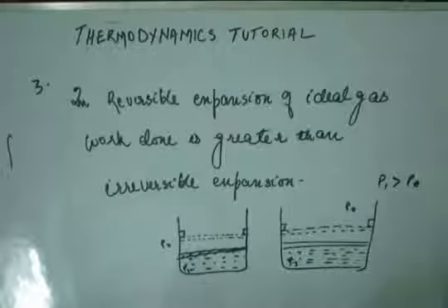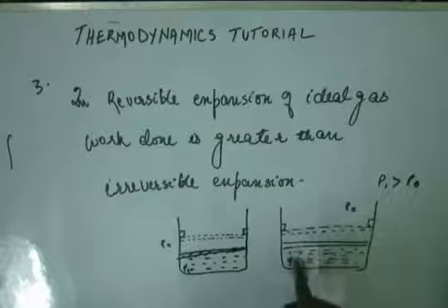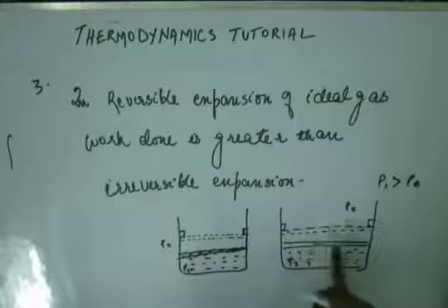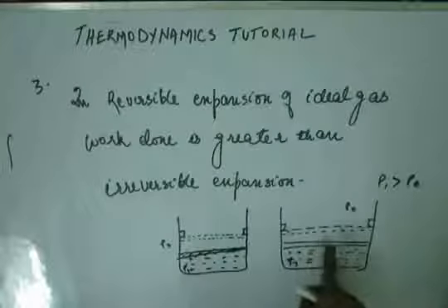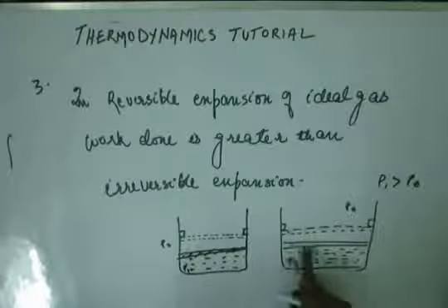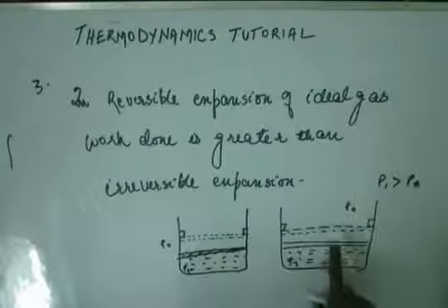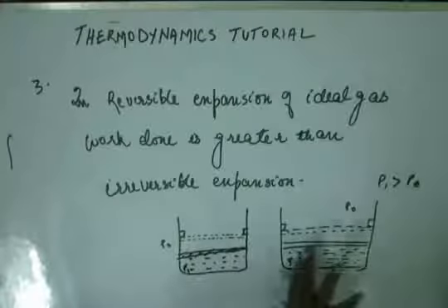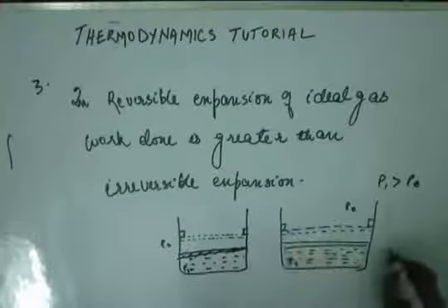Now in this case, if I have to calculate work, suppose the moment I remove my hand, what's the work? The moment I remove my hand, the resistance that the piston has is only the pressure from the surrounding, that means the atmospheric pressure. So the piston will have to go against pressure P0. So the work done in this case by the piston will be